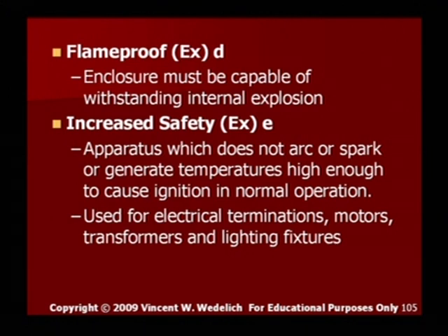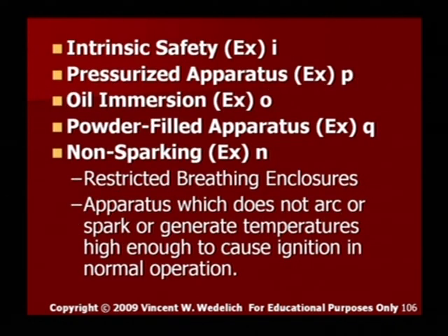A transformer has just coils. There's no arcing and sparking devices in it, and it could be classified as EXE. Your intrinsic safety, EXI, pressurization apparatus, EXP, oil immersion, EXO, powder filled apparatus, EXQ, non-sparking, EXN, restricted breathing enclosures. Apparatus which does not spark or arc or generate temperatures high enough to cause ignition in normal operation would be a non-sparking EXN enclosure.